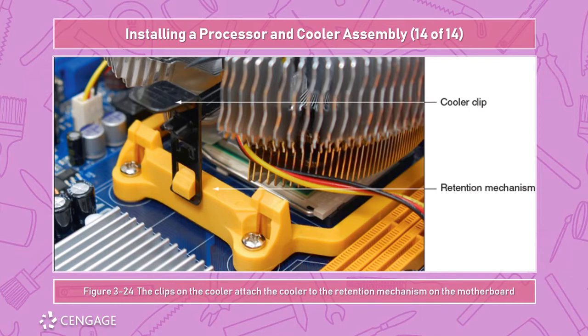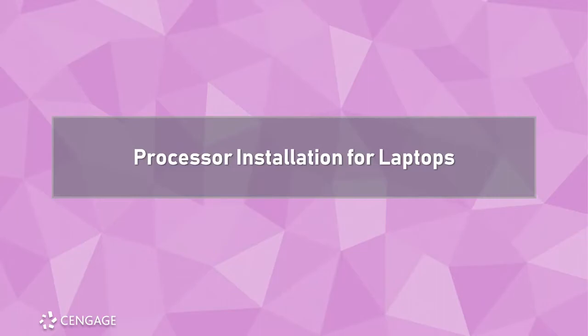Instead, here we're going to use a cooler clip. It has 1 clip on one side, 3 clips on the other, and it uses leverage of a bar that goes across the heatsink to hold it in place, as opposed to the lock pins. Now, this is an older AMD system. As I said just a little while ago, the newer ones, the Wraith, like tower coolers and stuff, they screw into posts the same way that an Intel set would.